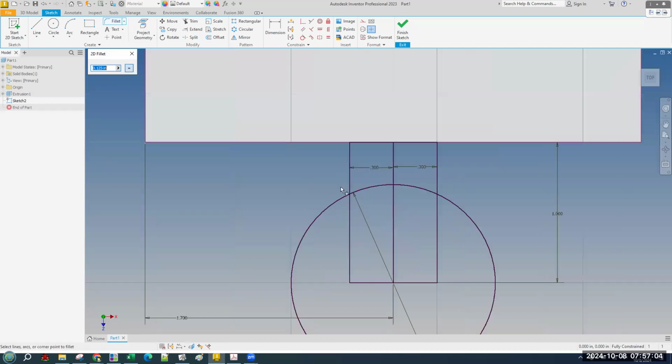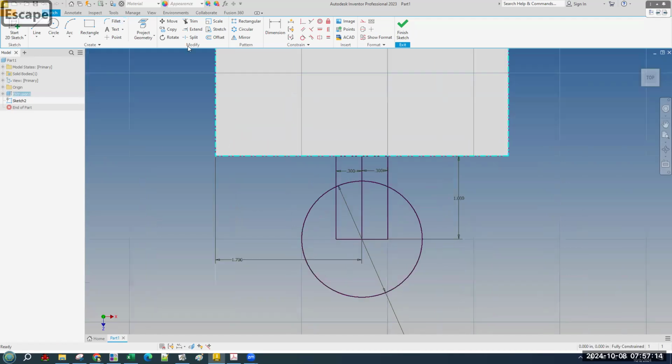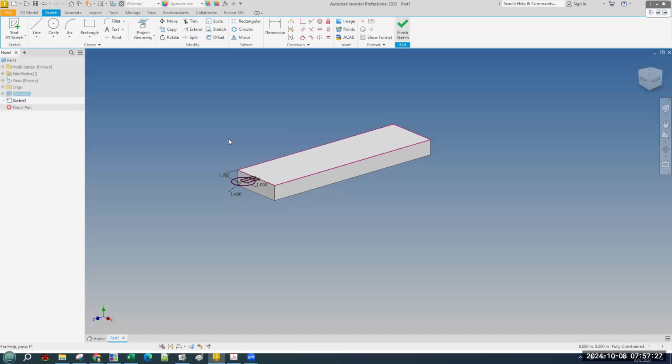And I think the fillet goes, okay, first of all, if you can't tell from my tone, don't do this. But the rounded over edge, you can, oh, it's not going to even let you do that in sketch mode. But either way, for fillet and for chamfer, we are going to prefer to do it in part mode once we have some material to actually fillet. Okay, so our sketch is complete. We're going to finish sketch.